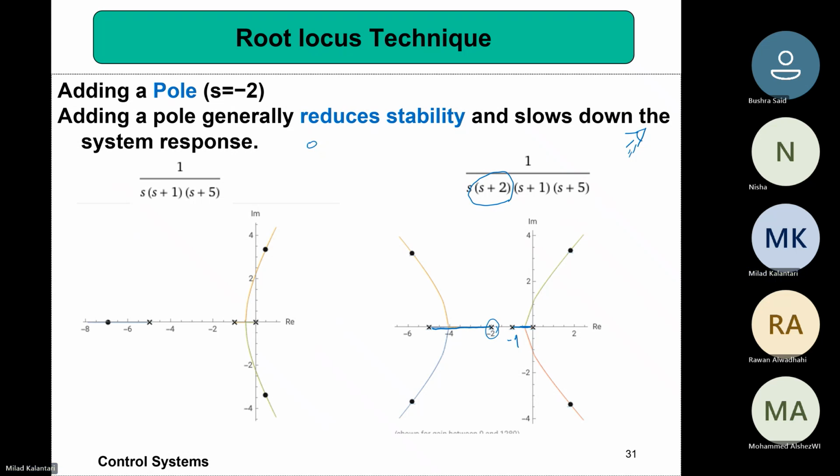So you have 1 pole at 0, 1 pole at -1, 1 pole at -2, and 1 pole at -5, right? You sum it and divide by 4, which is the location of the average of these poles. Is what? -8 over 4, -2, correct? So basically, when you are seeing everything from very far, you think that all of the poles are at -2.